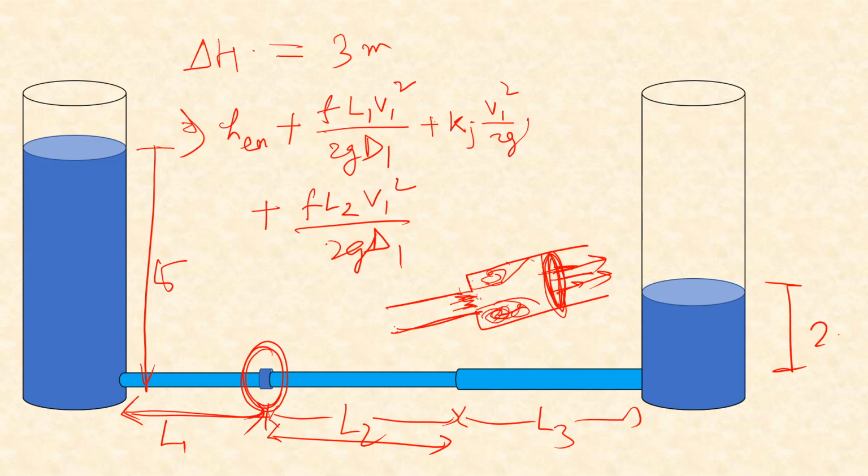And because of that, while flow is taking place like this, some flow will come back and cause this kind of turbulence. And because of that, some extra head will be lost. Whatever velocity the fluid has while flowing in these turbulent eddies could have been used in flowing in this direction, but now that energy is lost just in moving around in these eddies, and that energy will be lost by creating sound, then heat, vibration, etc.